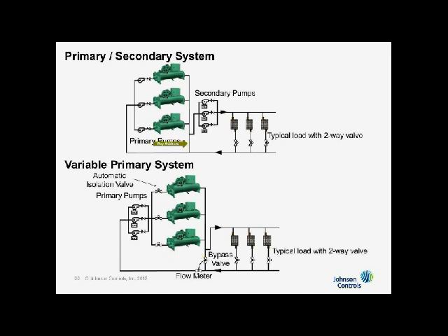With my primary secondary, we have a larger bypass whose design criteria is typically the same size as the headers. It's usually 8 to 10 pipe diameters long in order to prevent transient temperature exchange, and it's usually designed to be as close to zero pressure drop as possible. This, however, is much, much smaller. The pipe is sized to be roughly the same as the minimum flow of the largest chiller you have, or operating chillers. So it's much smaller, and we do need a pressure drop, which we'll explain a little more about later.